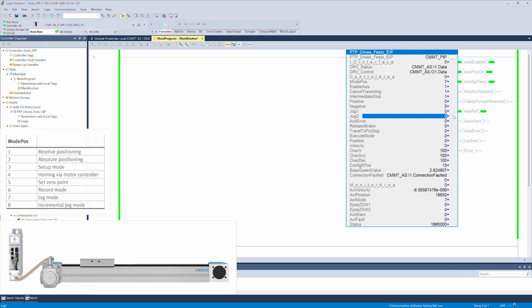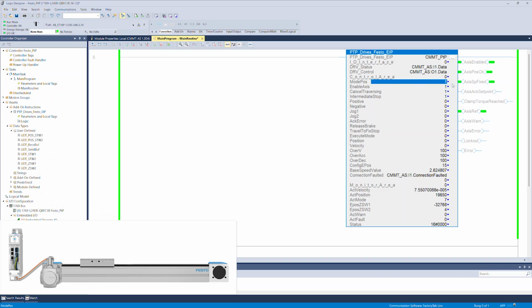Relative movement. Enter the mode pause value as 1. The parameters of the factor group define the resolution at which user units are scaled for transmission using the fieldbus. This value can be found in the Festo Automation Suite project. Open the CMMT-AS project.